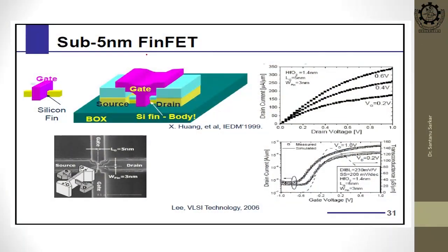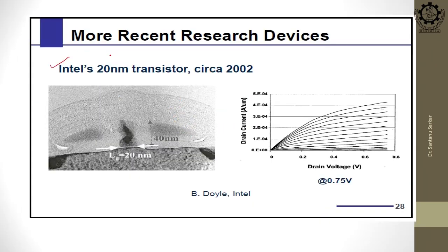Crosstalk means it will be affected by the adjacent signals, which will get coupled. It could falsely turn on, or the leakage current will get larger. So, these are the different challenges. To overcome that, in sub nanometer technology FinFET is preferred. In the previous case L was 20 nanometer. Now, in MOSFET it is very difficult to have the desired output. As you can see from this current characteristic, the slope in the saturation region is getting larger and larger.